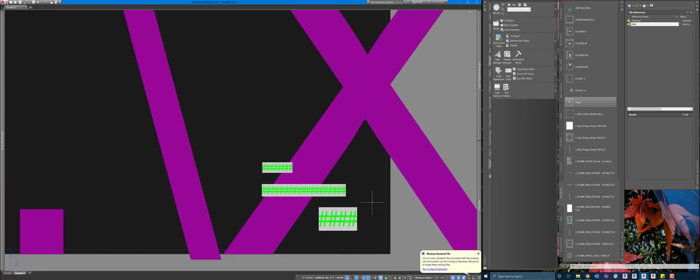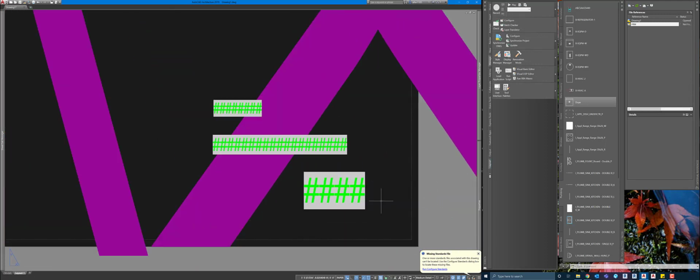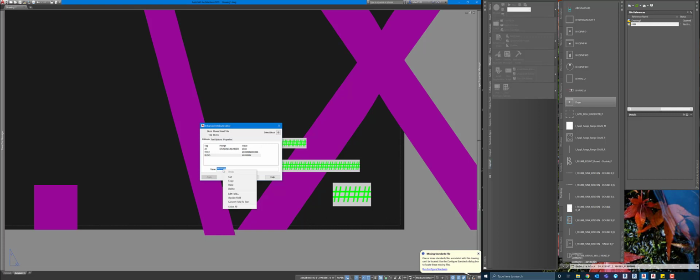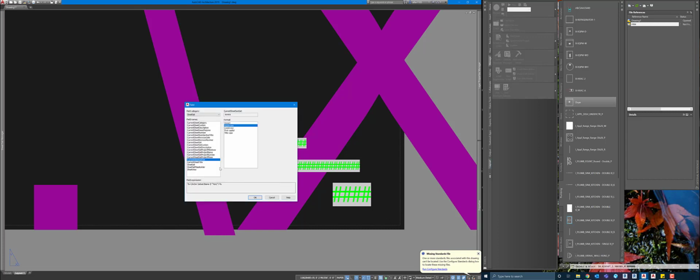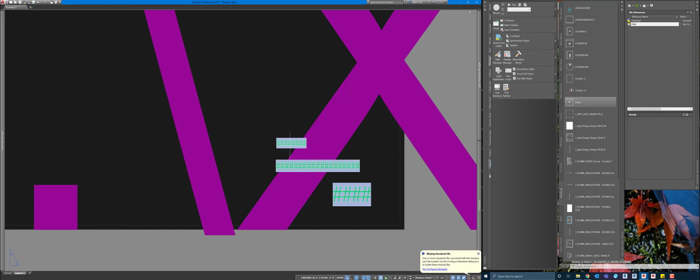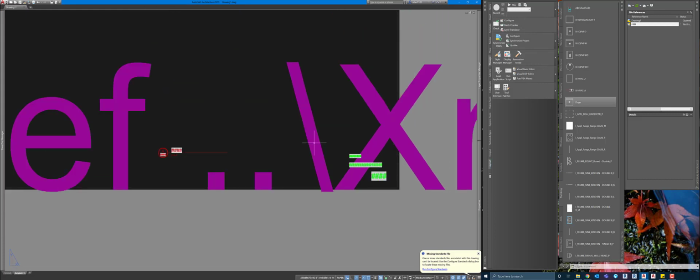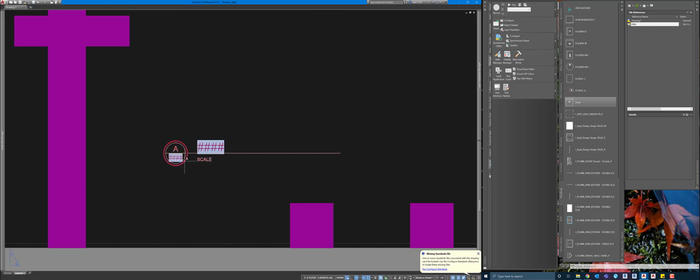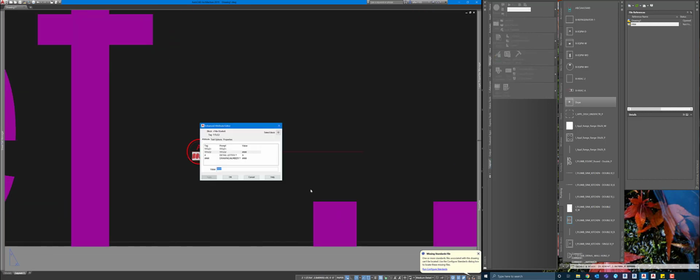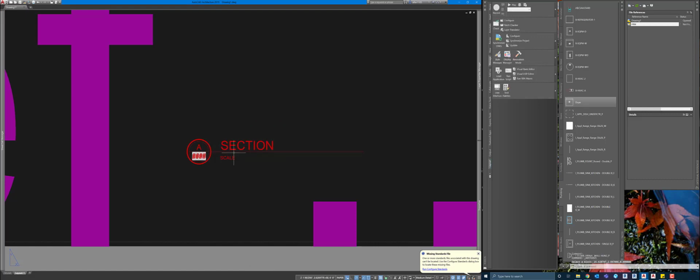Now I want to make a point that any of these gray areas in this block, these are fields. You can edit a field. I'm going to double click and then right click and you can say edit field. And I want to make a point that you can also create new fields. Anything with multi-text or text, I believe you can turn into a field by right-clicking on it and saying create a field or edit field. And these properties link back to the sheet set or a particular value within that sheet set. So logically, this is going to be the sheet number, the sheet name, and the discipline or the subset that that sheet is in. Same with these tags. This is going to be the sheet number. This is going to link to the sheet name. I want to make a point that at any point you can come back in. If it's a field, you can just rename this title block, and that field will just go away.